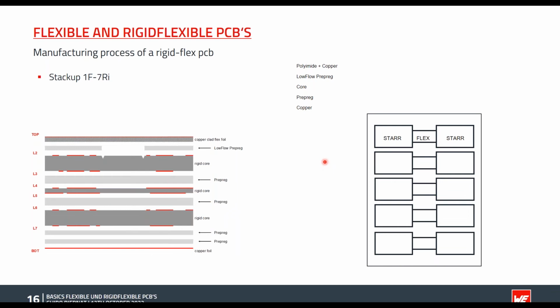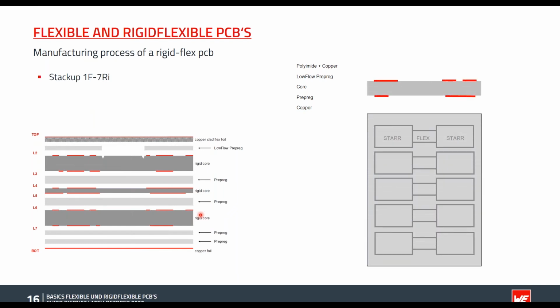First of all, we want to produce the inner layers. The starting materials are FR4 cores, laminated on both sides with copper. The FR4 base material now runs a process sequence: cleaning, laminating, resist, exposure, developing, etching, and stripping. The PCB layout is now visible in the copper structure. This is an FR4 core with your layout.